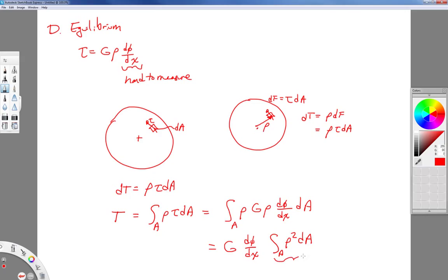And because it's about a polar axis, in other words, an axis that's coming out of the page at us, it's called a polar moment of inertia, I sub p. Now, typically in a calculus class, you would derive this formula. We don't have to derive that formula in this class. I'm going to write it down, and actually it's in the appendix or the back cover of your textbook.